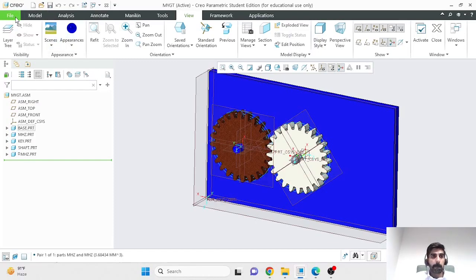When you're done with your assembly, you have to package that, and remember that the assembly is just a platform where individual parts are being imported and displayed with particular orientation. So you need to have those individual parts available.